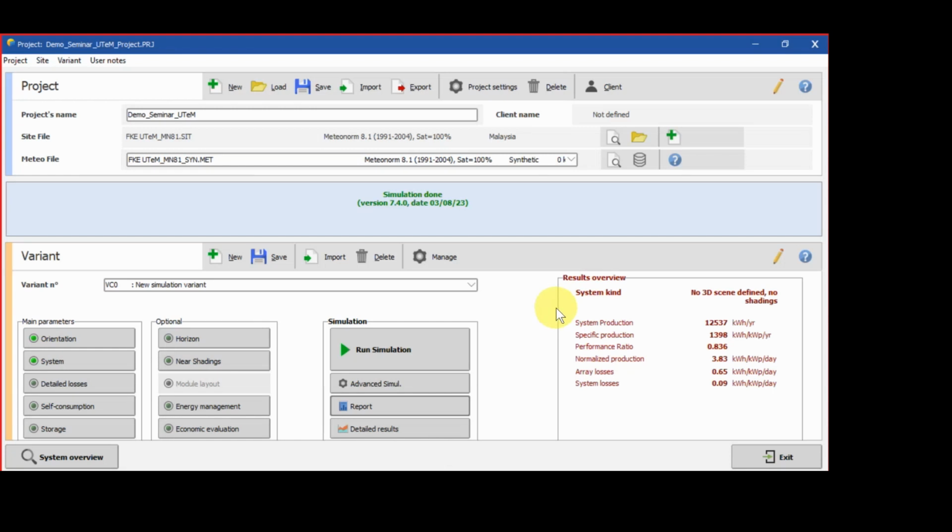Multiple year individual record. Currently for PVSyst, it doesn't generate for multiple years because it assumes the same profile is repeated. The cycle is repeated every year. But if you have your own data, for example, where every year your irradiance profile is slightly different, then you can put it in and run your simulation on your own. That is quite advanced, I think, but it's possible if you have your own data.